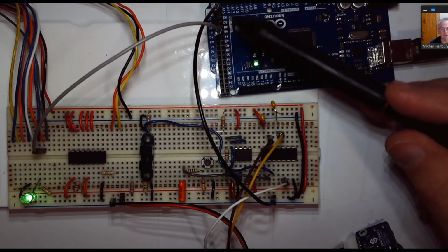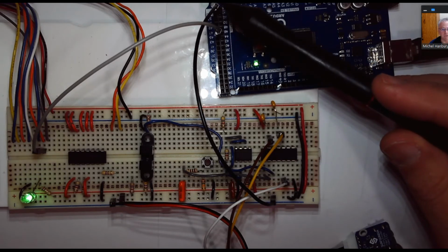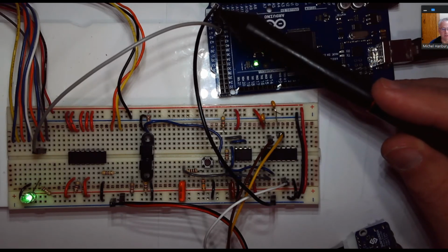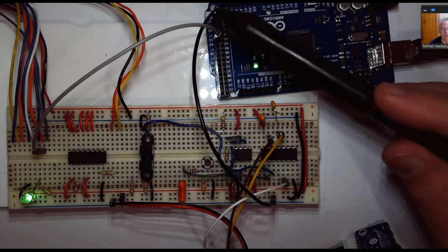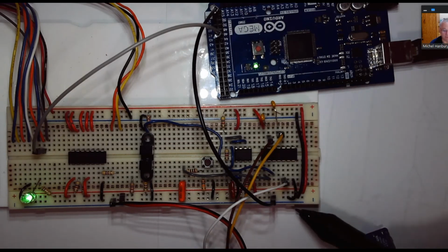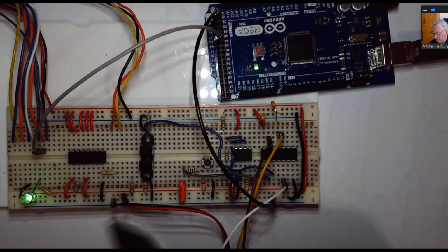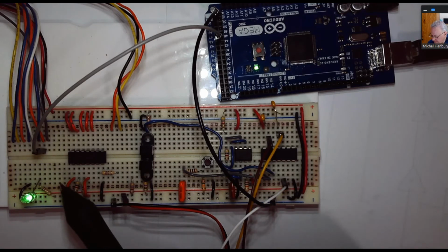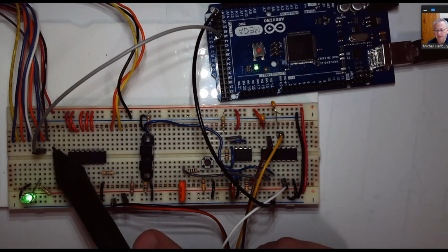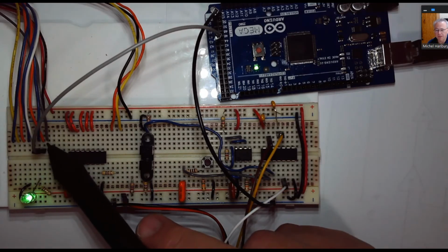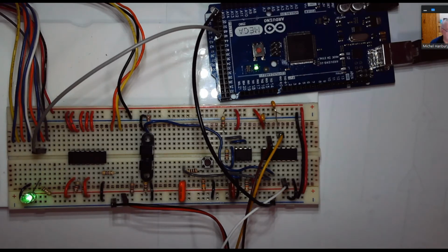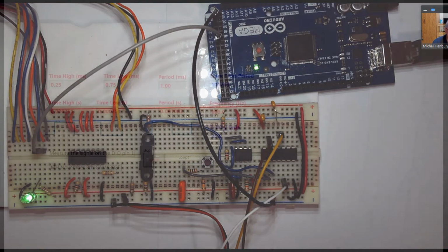You can see here that I've connected, it might be hard to see, pin 45 on the Arduino, and I have to have a ground reference, only the ground. I don't need to connect to the supply. So I've got the ground pin on the Arduino going to the ground pin on the MDAQ interface board, and I have pin 45 going to digital I/O1. It's kind of hard to tell, but the first wire is 0, the second one is 1, and it's going to digital I/O1. So now we'll go back to the MDAQ software to have a look at that.